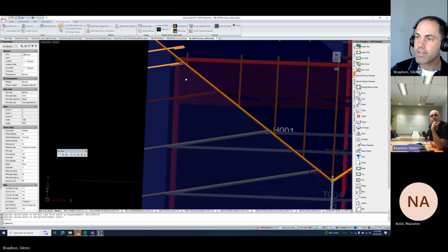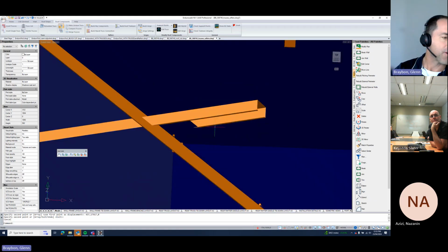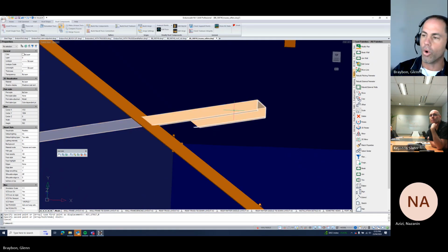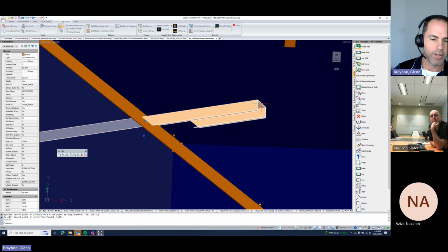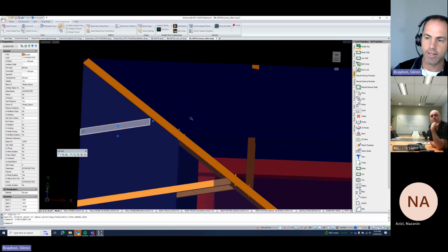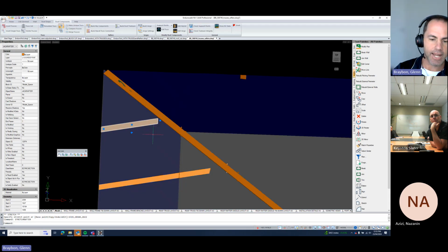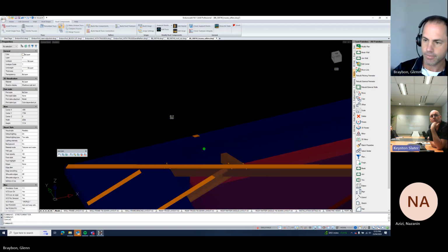It doesn't cut it back to the hip. Well, that was because I used copy and not a copy rafter. So you have to remember the difference between using a CAD command or an EC command. When I use commands like copy and move, without move rafter or copy rafter, it's not necessarily going to rebuild. Does that make sense? Yeah.